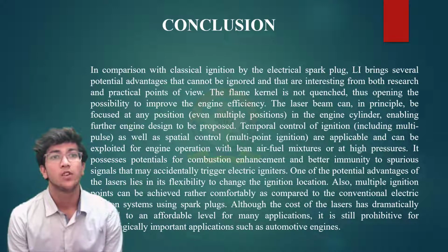It possesses potential for combustion enhancement and better immunity to spurious signals that may accidentally trigger electrical igniters. One of the potential advantages of laser lies in the flexibility to change the ignition location. Also, multiple ignition points can be achieved rather comfortably as compared to the conventional electric ignition system. Although the cost of lasers has dramatically reduced to an affordable level for many applications, it is still prohibitive for technology in important applications such as automotive engines.